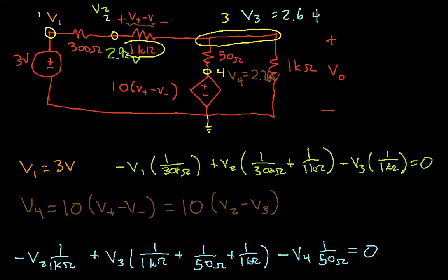But as we increase the input resistance, which is 1 k ohm, and as we increase the gain, so we change the input resistance from 1 k ohm to 1 megohm, for example, and increase the gain to 10,000, then this output voltage would get very, very close to 3 volts. Okay, so for a real op-amp, again, this output voltage would be very close to 3 volts. And again, if you want to, you can go and make these changes in the computations and verify that what I'm saying is true, just in case you don't trust me not to lie to you.